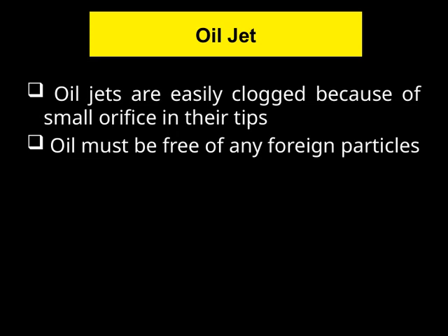Oil jets are a critical component in many engine systems, but they can be quite sensitive. One of the main challenges is that they are easily clogged. This is primarily because of the small orifice in their tips, which makes them vulnerable to blockages.